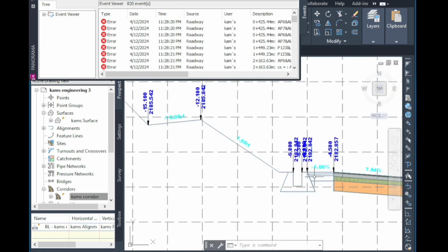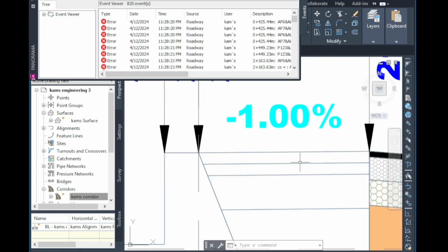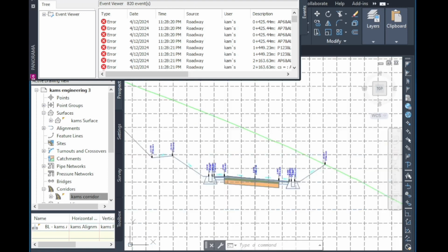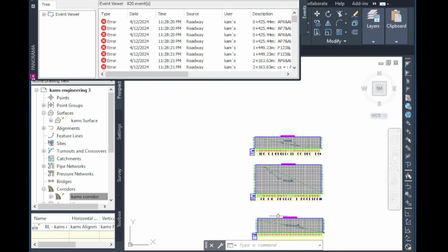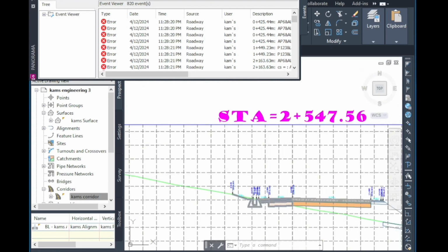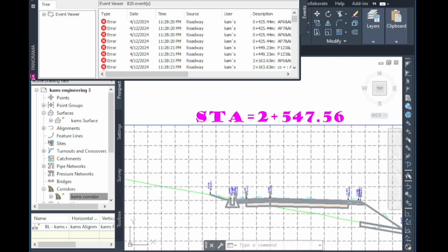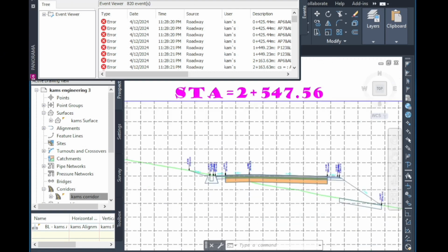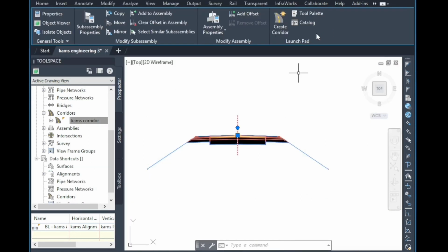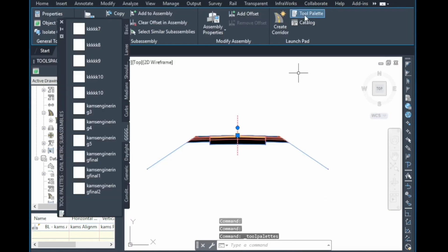Our ditch changed to masonry U-shaped ditch, and our shoulder layers changed to 3. You can also change all ditch dimensions, all cut and fill slopes, and so on. Let's change the ditch to trapezoidal. All parameters are changeable. And also check our cut, undercut, and replacement case.